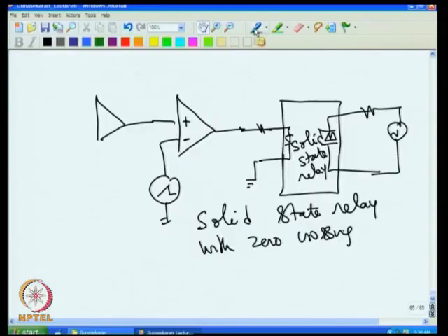If they are not protected against short circuit, then what essentially happens is one day or other somebody will be, without their knowledge, shorting the load, and the MOSFET or transistor will get destroyed. So if it is given to a user, any transistor or MOSFET drive, it must be protected against short circuit. The thyristor, one good thing is the thyristor can be protected using a fuse. In fact, this is the only device in electronics that can be protected using a fuse. No other device can be protected using a fuse.